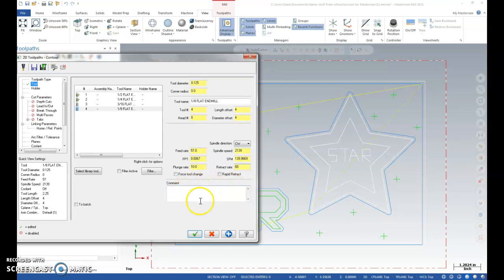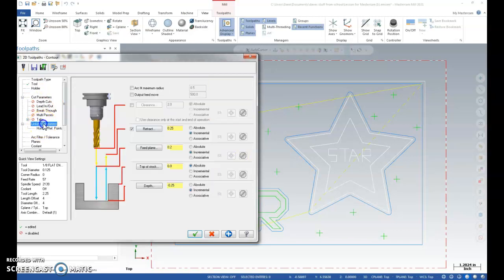And then you can actually write in here what you're doing. So I'm going to say like, around all items. You could say down 0.25 inches with quarter-inch tool. It's up to you. Sometimes it's helpful to stay organized. Okay, great. That looks really good. I already know that the linking parameters is right. So he's already at quarter because it kept it from the previous toolpath. So I just checkbox it.